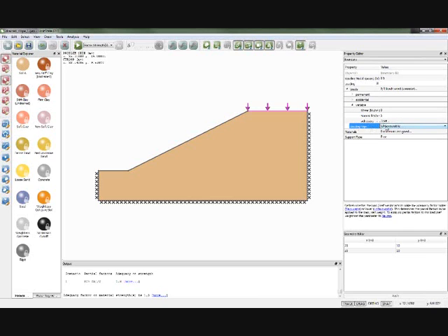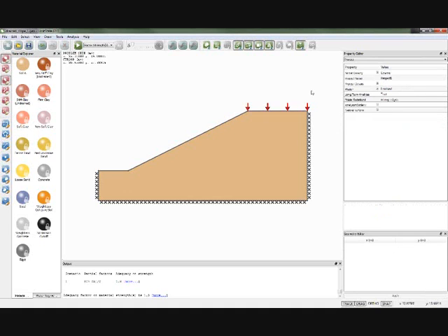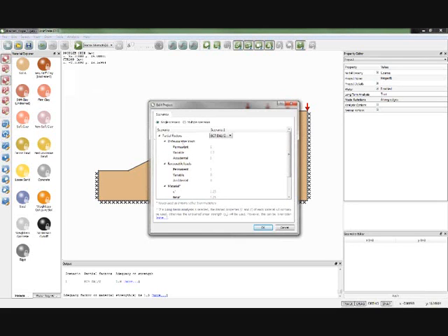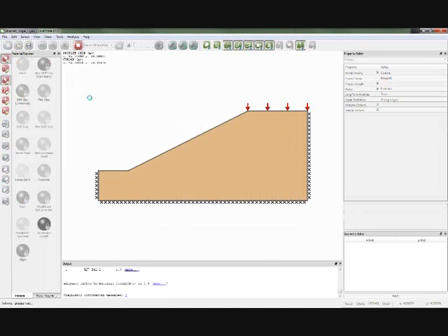And we should check that that's unfavorable. So it's set to unfavorable. I could set it to favorable or neutral. Neutral isn't a Eurocode setting, but it's put there in the software to say don't apply any factors at all. But we want it to be unfavorable. And now if I solve the problem, that load of 5 will be pre-factored by the unfavorable variable factor of 1.3. So I can run that through the software, solve that.